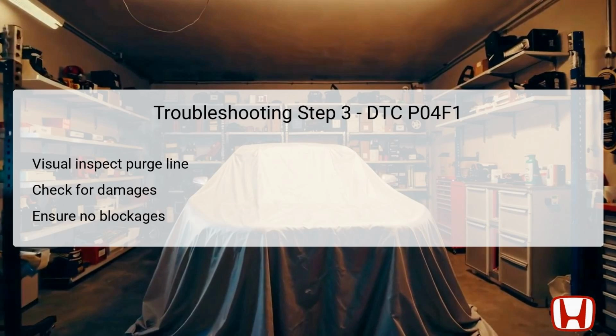Properly functioning lines facilitate the smooth passage of fuel vapors from the canister to the intake manifold. Pay close attention to the integrity of the connections at each end of the plumbing, as poor connections can also be sources of leaks or airflow interference.